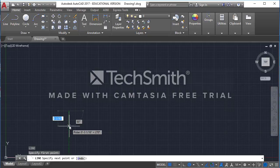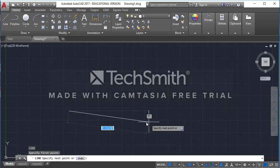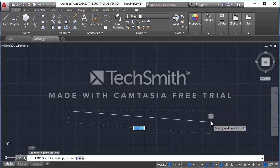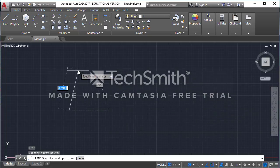What this is doing, in AutoCAD, is referred to as ortho, O-R-T-H-O. What that actually does is it keeps you drawing in 90 and 45 degree angles. Right now that's not currently activated, as I can draw on any angle that I want. But as I move my mouse down, notice this little green line is giving me a dimension. It's saying this is 8 5/16 of an inch, and it also says I'm drawing at a 90 degree angle. As I move my mouse around, that angle will change, as will my dimension.